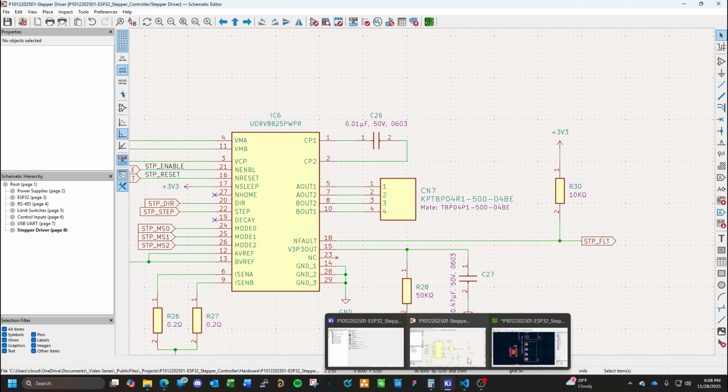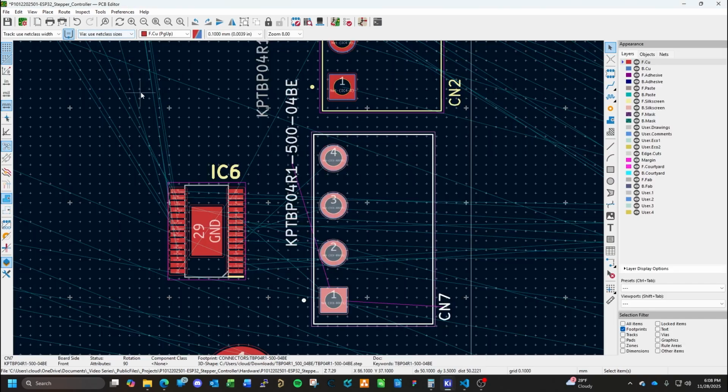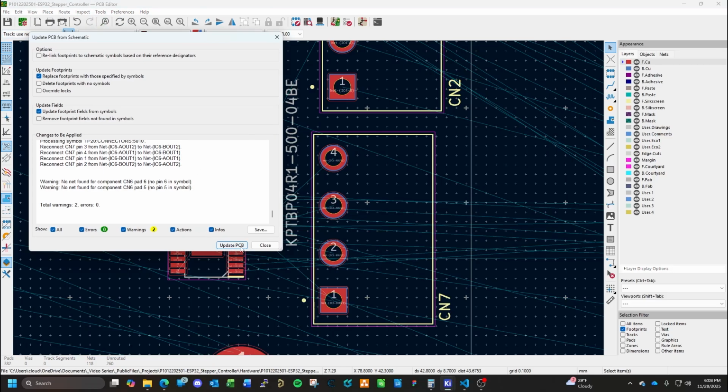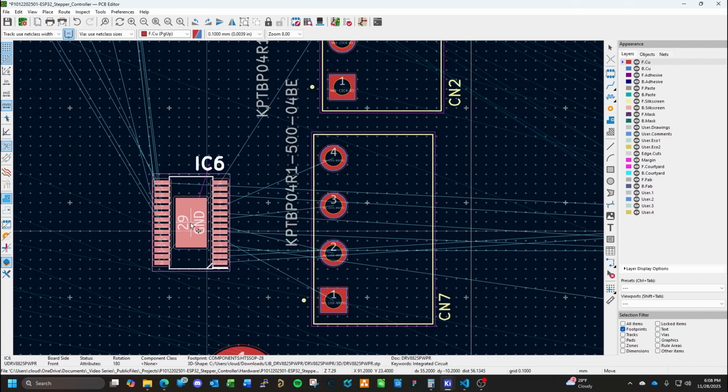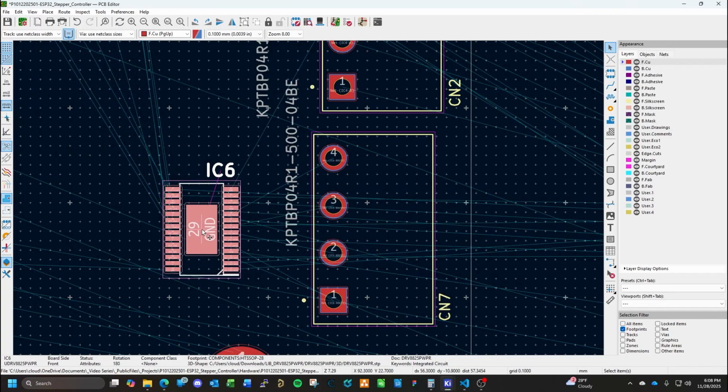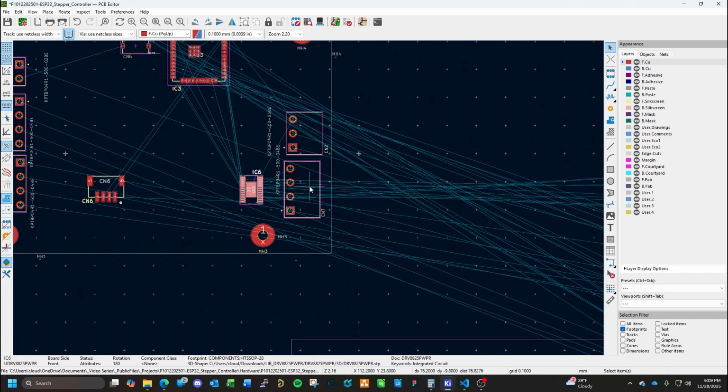We're going to save that, come back over to the PCB. Then we're going to save that, and then Tools, Update PCB, update, close. And now it should have redrawn those air wires. Now they're uncrossed. That's what I originally wanted so we can avoid vias where we can. They can just be straight traces from these pins over to these connections. No vias, no jumping layers, because we can handle it in labeling and documentation. It's fine to have weird, as long as things are clearly documented and easy enough for the customer to understand.